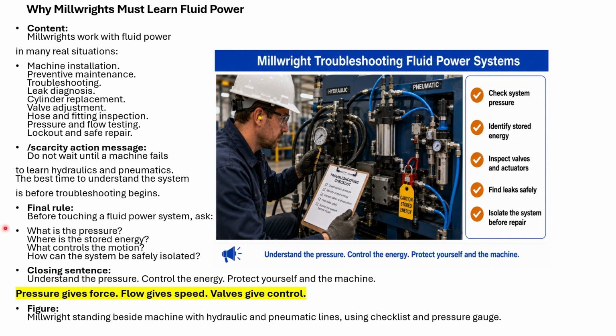Final rules. Before troubleshooting a fluid power system, hydraulic or pneumatic, ask: what is the pressure? Where is the stored energy? What controls the motion? How can the system be safely isolated? I give you a closing sentence: understand the pressure, control the energy, protect yourself and the machine.